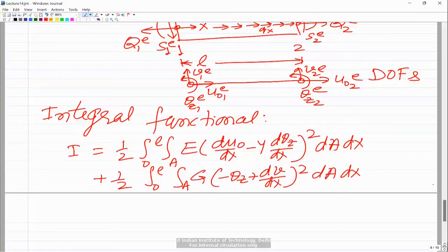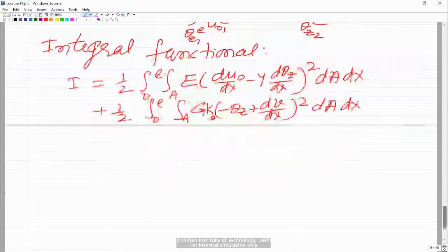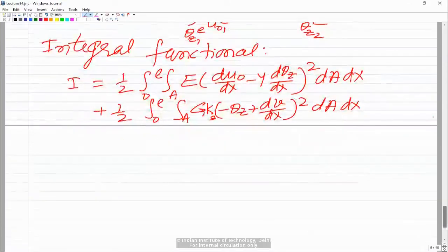Whereas in actual, if we look at the exact solution, it is parabolic. So to account for that, we introduce a factor which is known as the shear correction factor. So let me put that factor over here. I am putting here this Ks. Ks is a shear correction factor. I will write again what this Ks is. This is to get the actual strain energy due to transverse shear stress because of non-linear distribution of tau xy, the transverse shear stress, across the thickness of the beam.